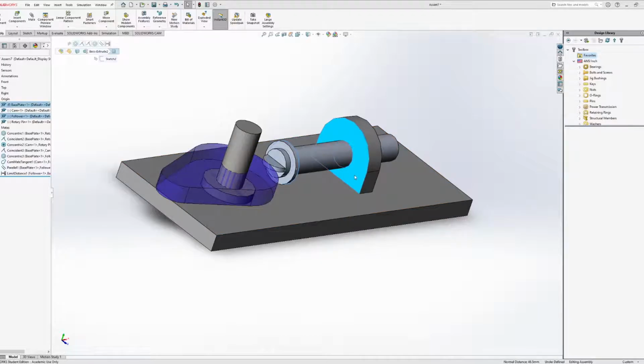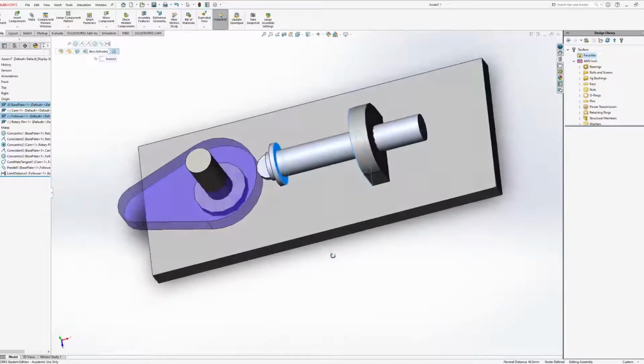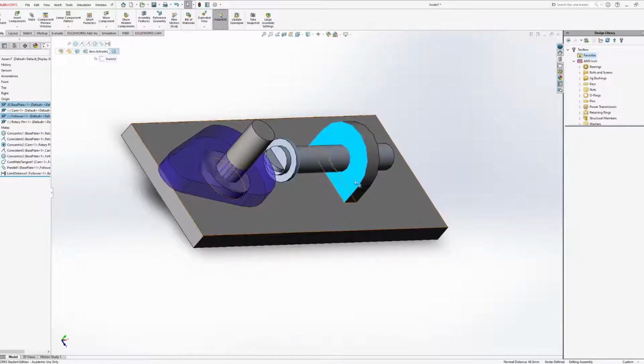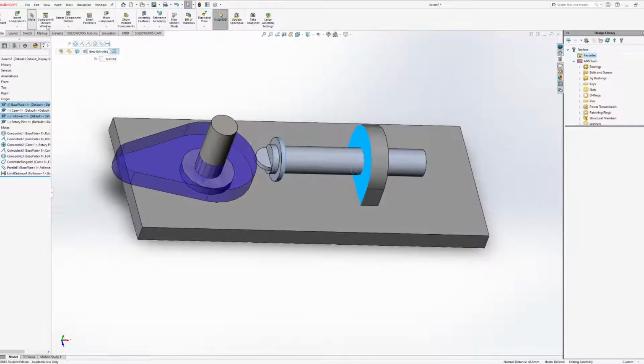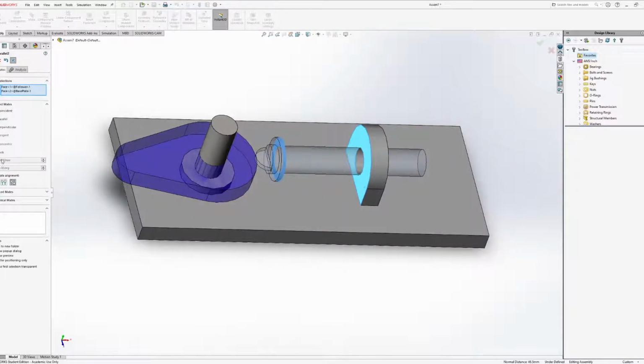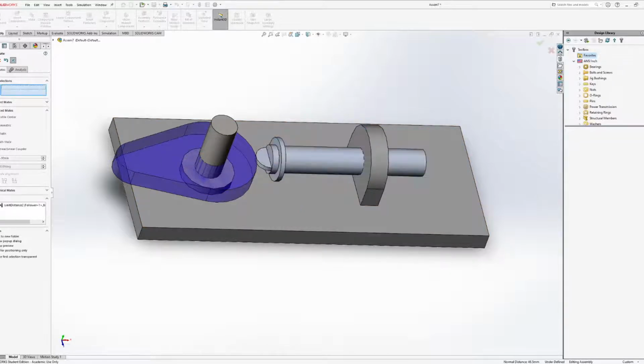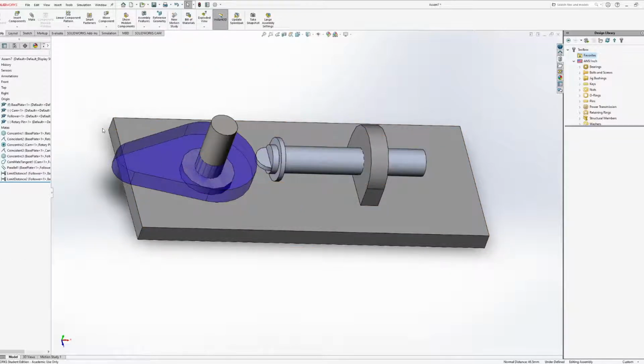These two, I can probably define these as well and say, hey, it can be about 47 at its maximum, and I want it to be 0 at its minimum. So I would probably create a mate there as well to say, okay, I want it to have a max of about 47, but a minimum of 0. And maybe that'll alleviate it.